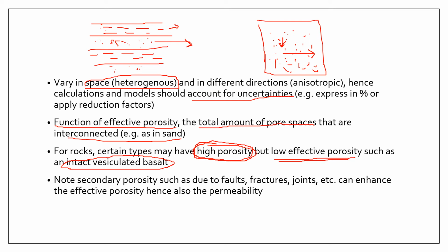Now, rocks can have secondary porosity, due to faults, fractures, or joints, which can enhance your effective porosity. As a consequence, they can increase your permeability or hydraulic conductivity.